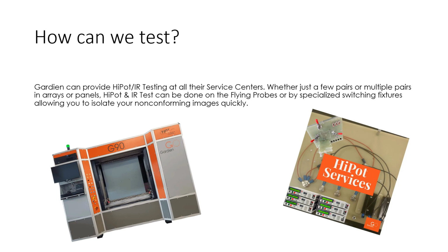The Gardien flying probe line can also perform this test for you. This is done by an integrated meter into the system itself, so it can do the opens and shorts general test along with an IR or Hipot test, and this can all be done in one session without having to remove the board from the machine and go to a bench type scenario, or even on the same machine having to reload programs, and that can introduce possible errors in handling.